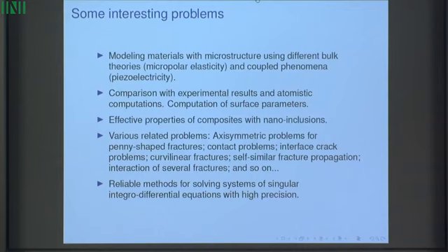Those Steigmann-Ogden conditions are of a relatively complicated kind, and when you try to write those conditions for a general contour, you end up with a big mess. Because of that, the majority of solutions which you see in the literature, whether for the Gurtin-Murdoch model or for the Steigmann-Ogden model, are typically either straight contours or circular contours.